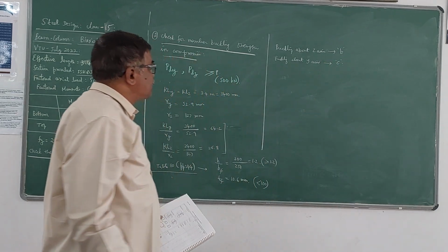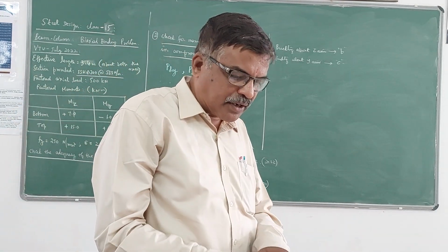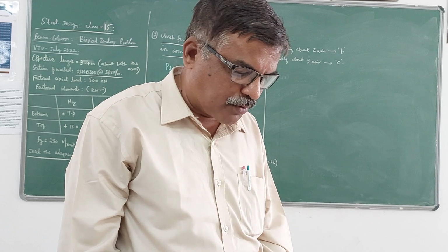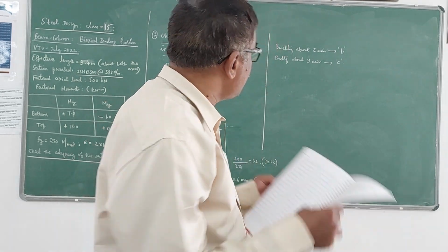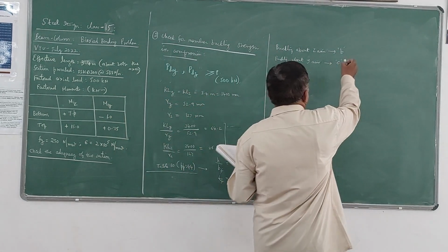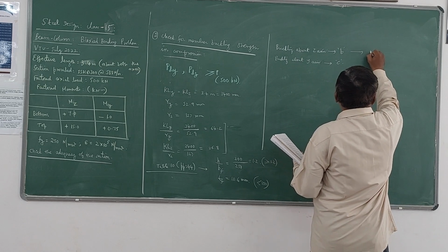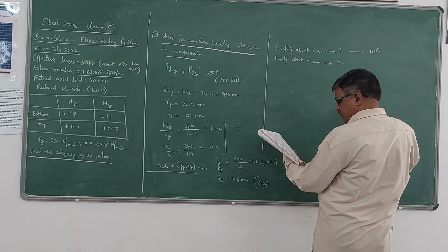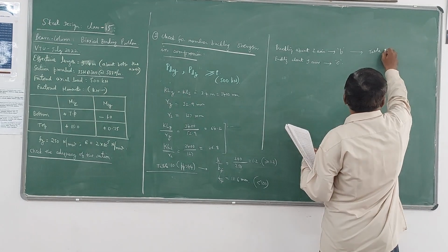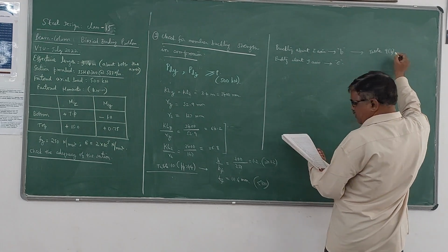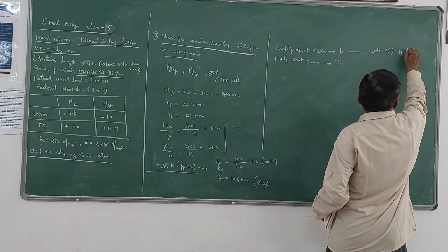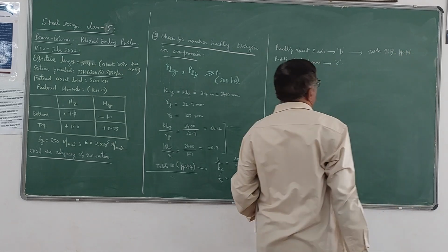Now based on this, you have to refer to the particular table given in the previous pages. If you take buckling about the z-axis, then you go to Table 9b, which is on page 41 of the code.